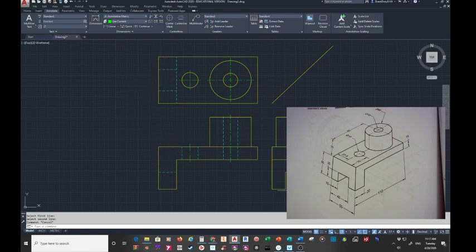Come over to the side view. This is the same as this. This and this line up. These two line up. Notice that the views, they're all lined up. Do you know why? It's kind of obvious. I have some people that will draw these individual views, either lined up straight across or in some weird configuration. And I'm like, look, they all have to be aligned so that you can line things up from one view to the other. That's the whole point of this.